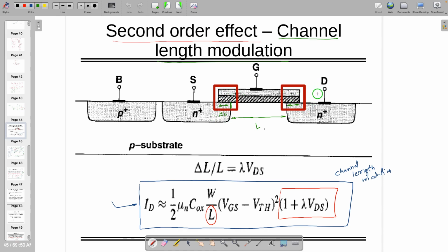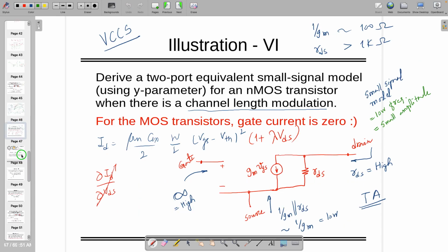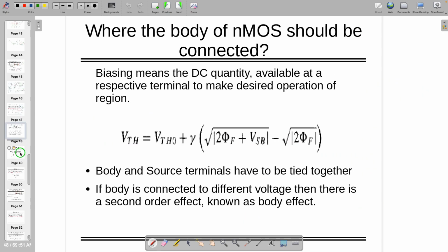Can you see directly the drain voltage? Drain is also affecting the current. Earlier it was like this, right? Drain and source didn't have any control over the channel. Understand? Gate was only controlling the channel. Now it's not the case. You see the possibility that drain and source voltage will also interfere, and that's what's happening, right? Okay, so if you understand that, then there is no problem.